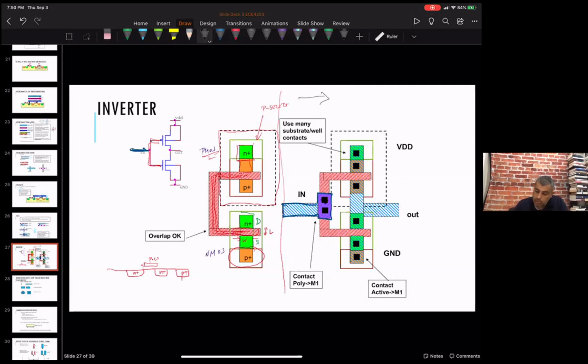So remember we said the more contacts, more vias, the better. So these guys have dropped in 2. And then they've also extended out their poly. So it got kind of fattened up here because we need an overlap of the contacts. And the design rules tell you exactly what that overlap needs to be.